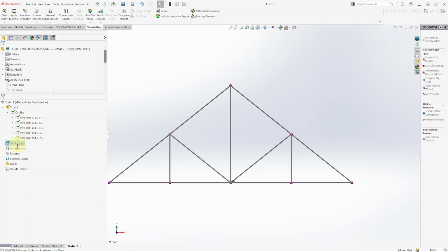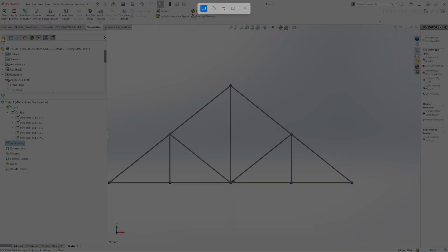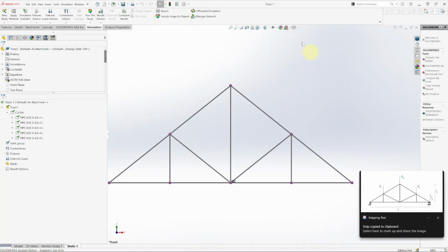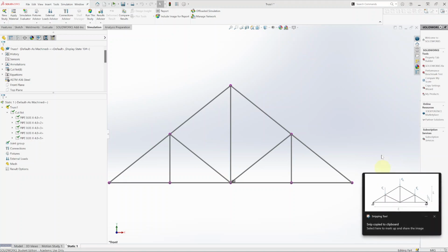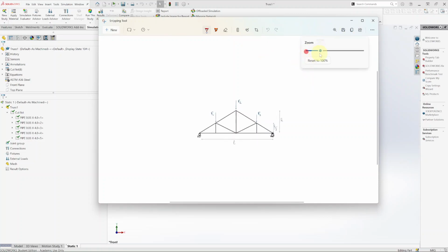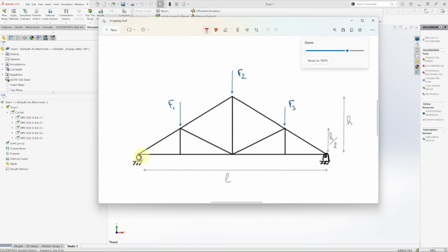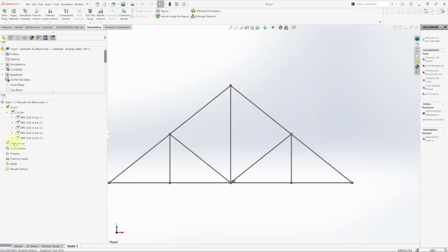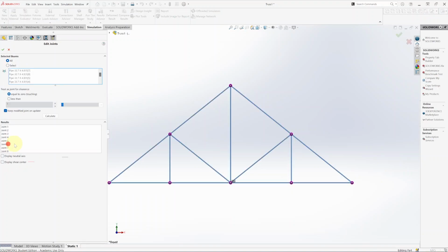Joint group. We will create joint where we have pin connection or a normal contact or a pin connection with the ground. Let me try to get my picture again inside the part. I don't know why I was able to get it first, but okay, I will keep it on the background and refer on it sometimes. So we will have a joint, a normal contact on the left, a pin connection on the right, and we will have pin connections everywhere where 2 or more members connect, 3 members. So joint group, and I double click on them.